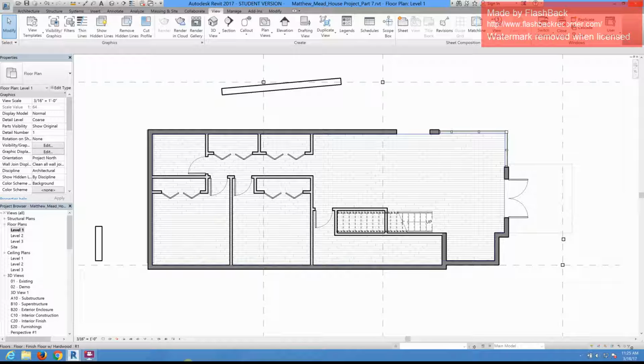What we're doing is we're creating the reference planes for our two different beam systems that we're going to create. We're going to create one beam system that's going to be a lower system, which is going to be all of our horizontals, and then we're going to create another beam system that sits on top of those. That's going to be our vertical beams, okay? So let's go through that process on how we're going to create these different elements.